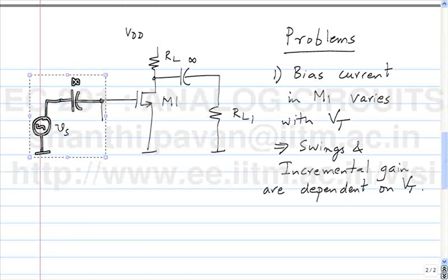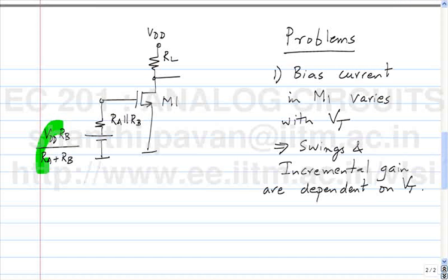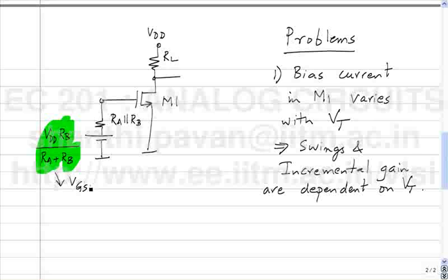So I will get rid of the incremental part. And as far as the biasing is concerned, the whole bias arrangement on the gate side is equivalent to the following, which is what we knew in the first place, which is VDD times RB by RA plus RB. Okay, and this is RA parallel. We had actually called this VGS1, and we said why bother with another battery, we can derive it from VDD. Okay, so this is in fact an earlier step than what we finally had.